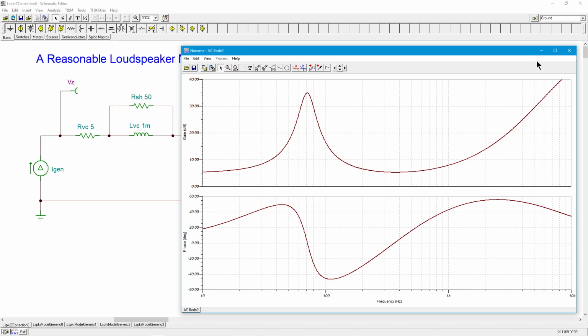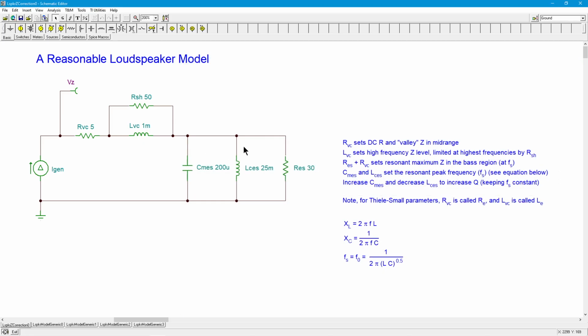All right, so the question then becomes, well, how do we do this? Because if you can imagine having a crossover, doing a calculation for 8 ohms, but then sometimes it's 30, 35, right? Sometimes it's 5. You can imagine that loading effect is going to really play havoc on the response of the crossover network. So we're going to do this in 2 parts. I want to take a look at a Zobel network, which is going to help us with the inductance. In other words, that high frequency bit that we see.